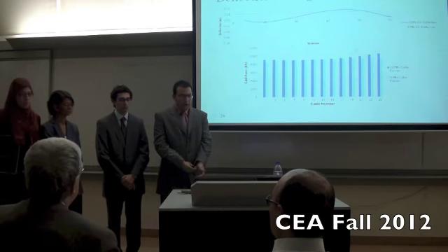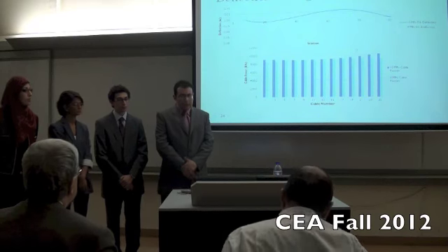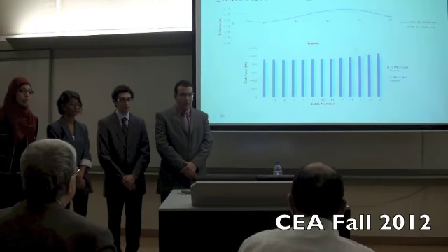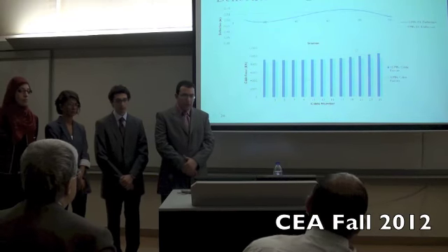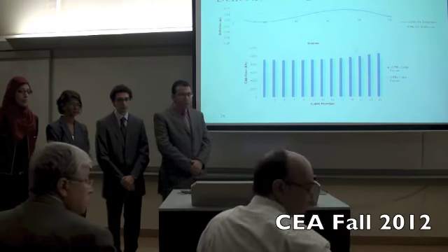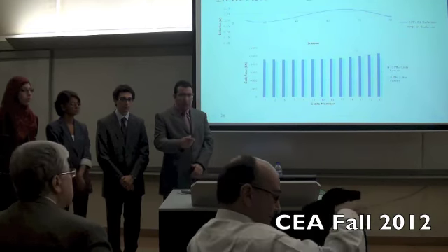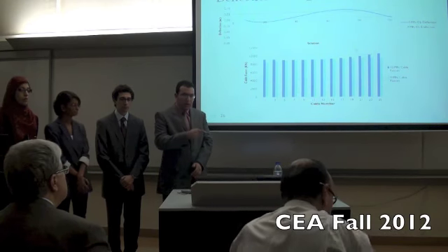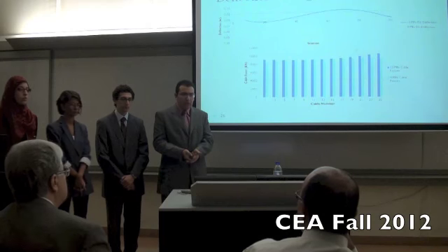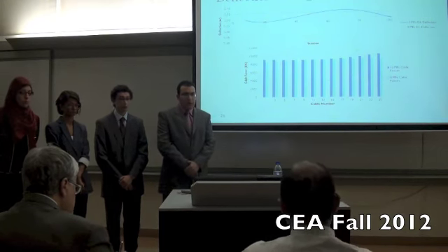We actually tried to calculate the cable forces by hand, but we had to solve like a 13 by 13 matrix to find the initial cable forces. So we skipped to the numerical analysis, and we kept checking our results with other existing cable bridges, and we checked also with our advisor and he confirmed.